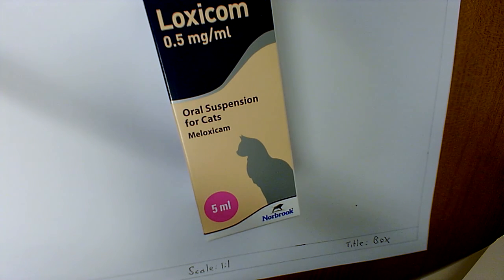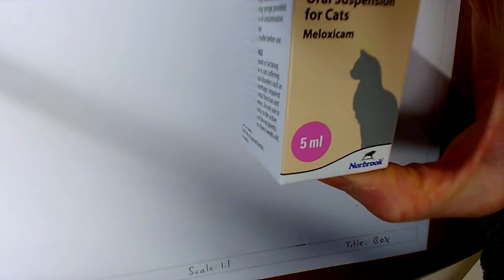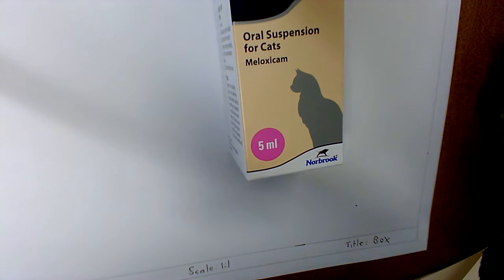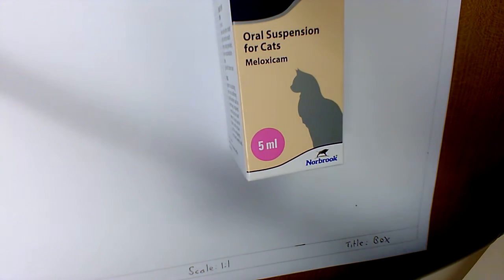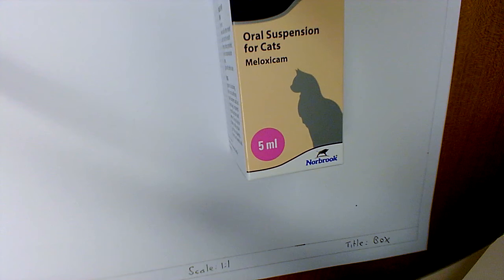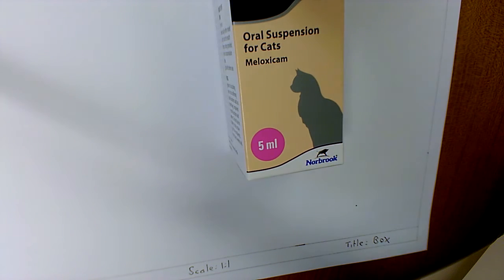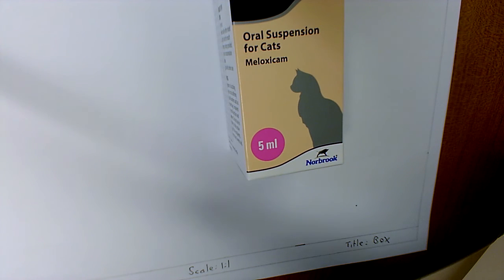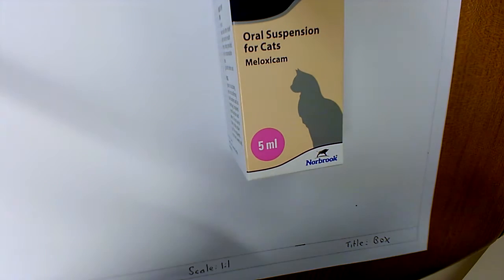Okay, in my previous video clip we looked at how to draw a net development as an orthographic drawing. This time we're going to look at a 3D object. In this instance I'm just using a box as a 3D object, and how to draw this as a net development. So if your project were some kind of piece of furniture, or a house, or some kind of building, you would do your orthographic drawing this way. You'd have a plan view, front view and the side views. It's slightly different, however it's the same thing depending on what you're designing and what your object is.